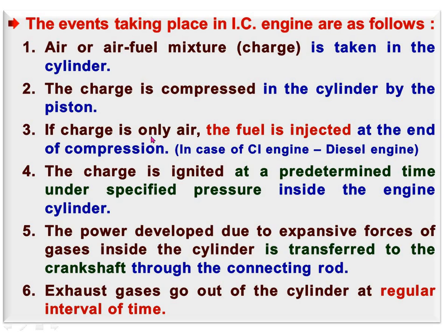If the charge is only air, the fuel is injected at the end of the compression stroke. Means in our diesel engine, or compression ignition engine, only air is taken inside the cylinder during the suction stroke, and fuel is injected when the piston reaches top dead center in the compression stroke.